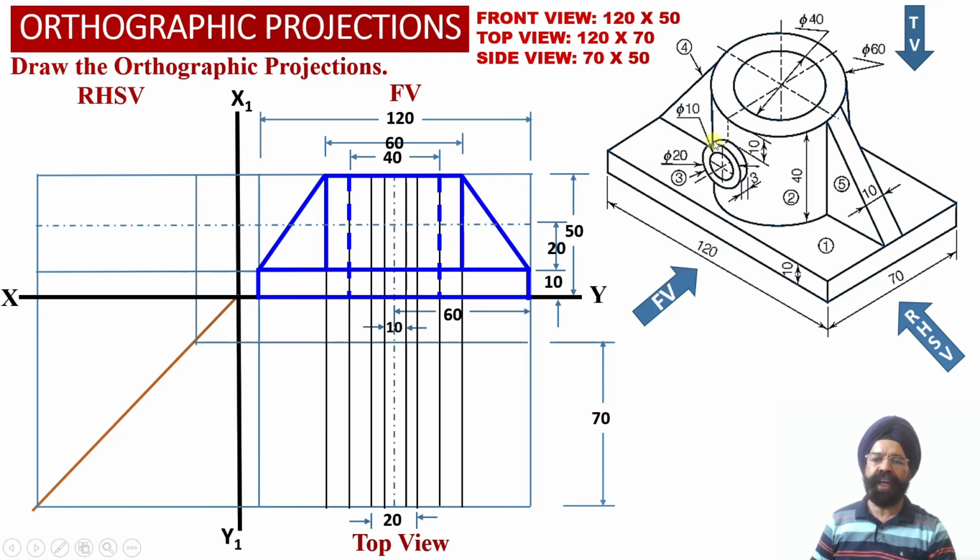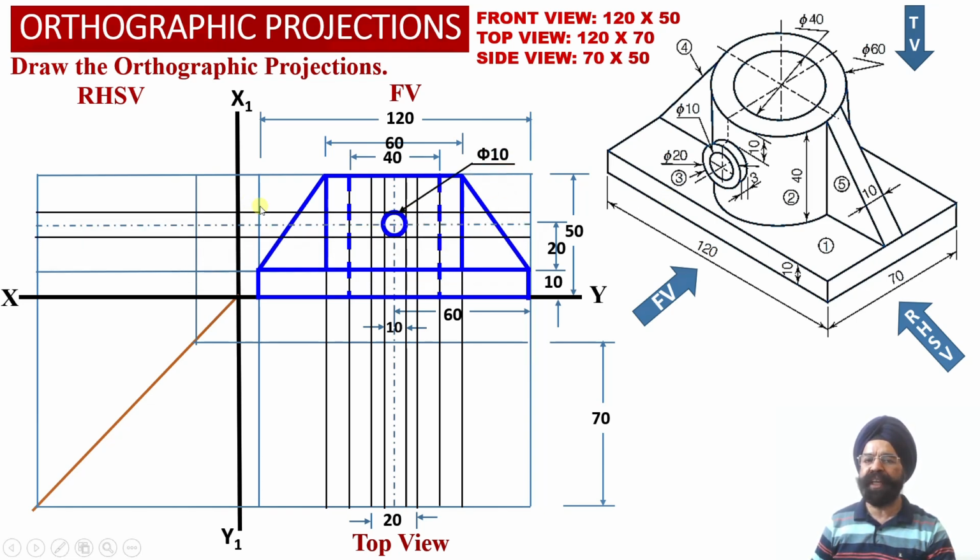So corresponding to the short cylinder, we know that the internal diameter is 10 millimeter and the external diameter happens to be 20 millimeter. So here we have obtained the internal diameter of 10 millimeter corresponding to this circular projection which we have obtained over here, and the true shape circular projection will be visible to us into the front view orthographic projection.